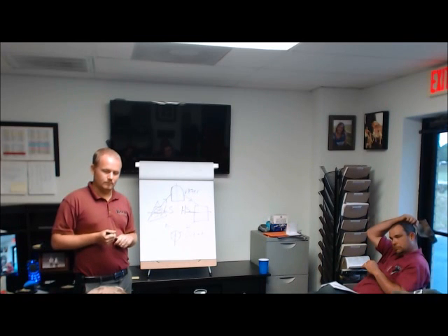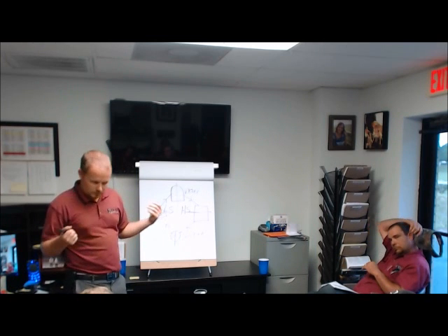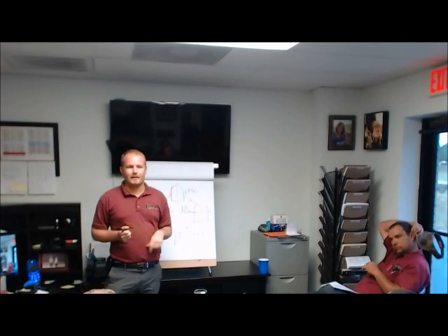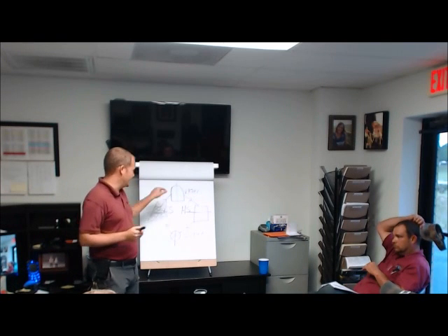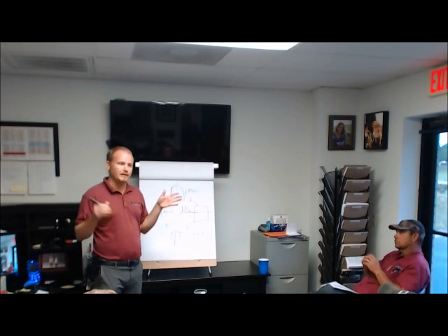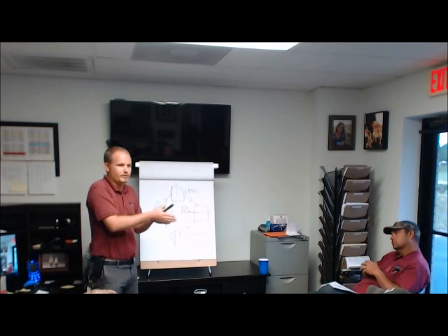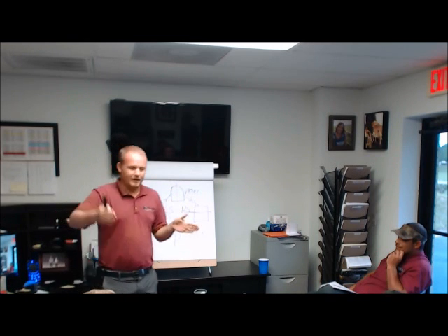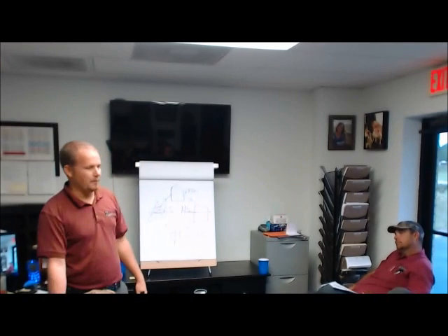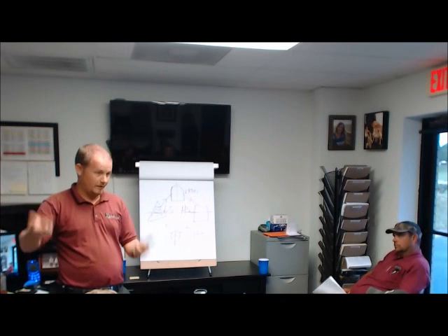What's the difference in temperature between what it actually is running, what the line is, and what the saturation temperature would be for that refrigerant? Correct. Jeff described it in an interesting way. What Jeff said is that it's the increase in temperature from the middle of the coil to here. That's a way of saying it, which is really saying a difference in temperature, an increase of temperature from saturation, meaning from the temperature at which it was boiling, to the temperature that it now is, that it's fully vapor. Because just like that 212 degree pot of water, you can only heat it more once it's fully vapor, and then you can continue to heat it and it will get hotter.